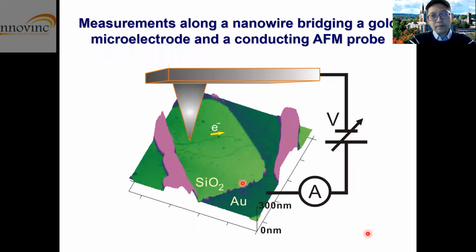And then, we place the 2 electrodes on the bacterial nanowire to do the measurement. But ideally, we should do a 4 probe measurement instead of a 2 probe measurement to eliminate the effect of contact resistance. Note that the bacterial nanowire is short. Placing 2 electrodes is already very challenging. It's more difficult to place 4 electrodes.